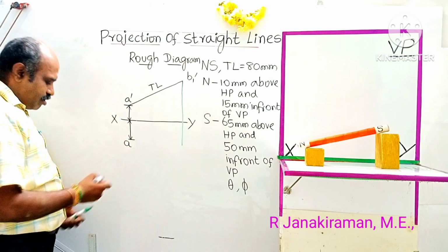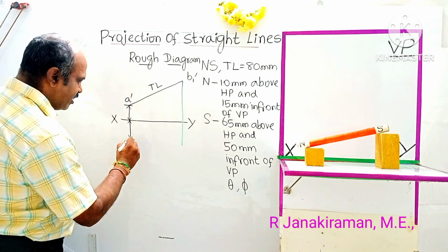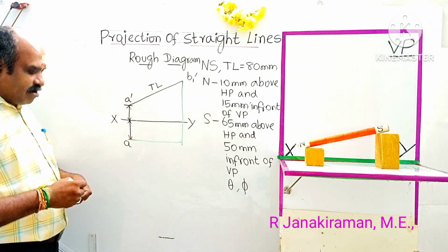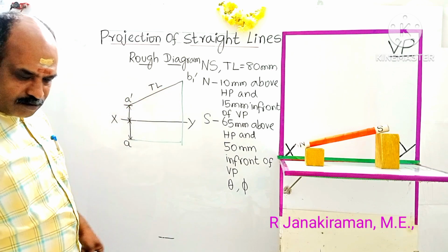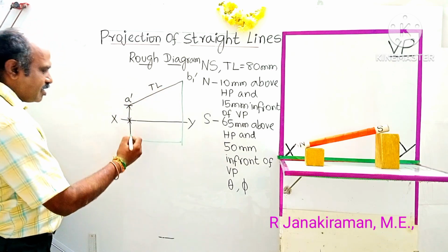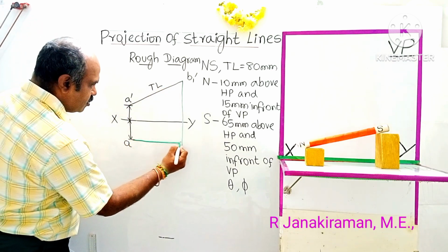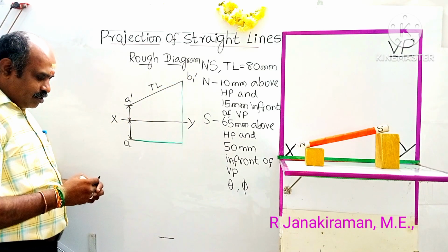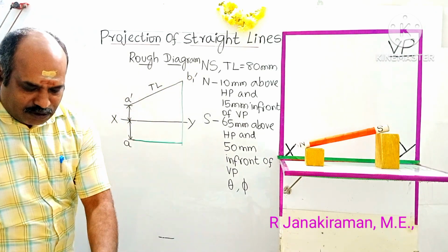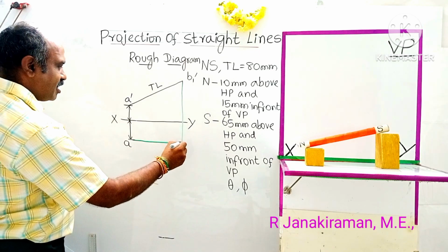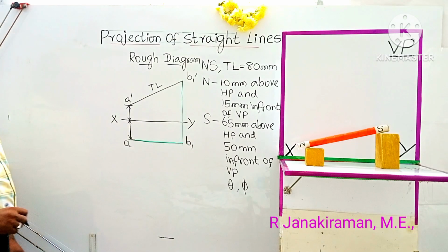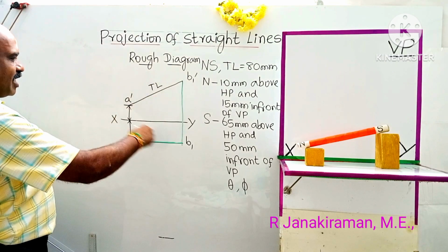Then you draw a horizontal locus line passing through point A. The point of intersection of this vertical projector and this horizontal locus line shall be marked as B suffix 1. We give a letter without a dash for the top view, so this point shall be marked as B suffix 1. Understand? So this step is carried out first.